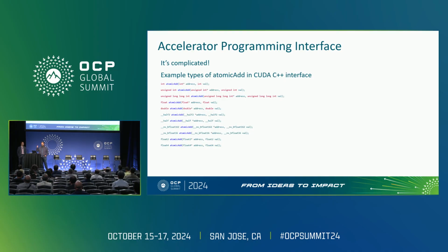And today you could try to support these on something like PCIe, but PCIe only has a couple different atomic flavors today. And all of these are something that you'd have to add into your protocol. Every time you want to do another flavor, you've got to put that into your protocol, do something different. And one way where CHI chip-to-chip really gives you a lot of power to hide this complexity is that you can have coherency. When you have a coherent interface, a lot of this complexity is just handled on the accelerator side.